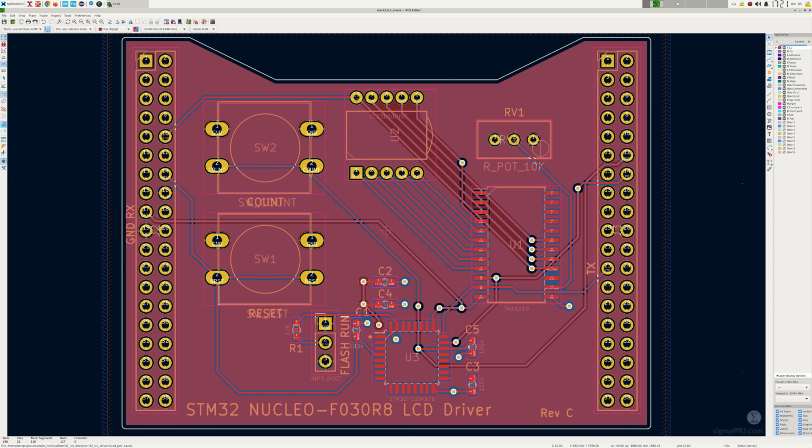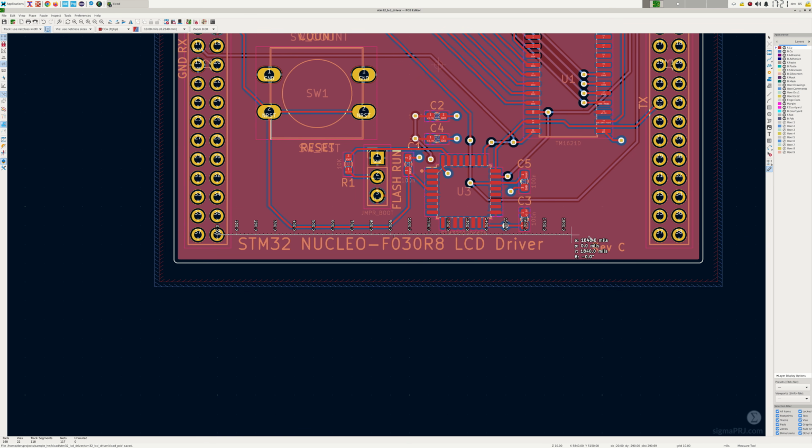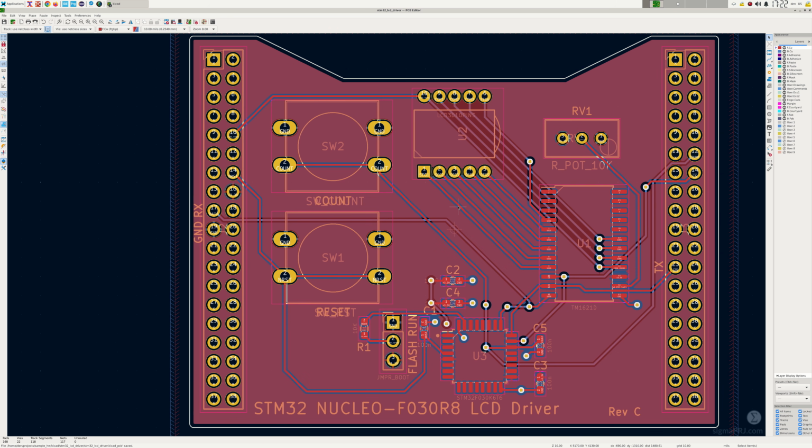Let's switch now to our PCB layout design. This has quite simple routing. It just contains 2 layers. And there is a principal measurement here which we have to follow. The distance between socket connector pins should be exactly 2300 mils in total. This way our adapter PCB will be pluggable into NUCLEO board without any issues. Here we can see the footprints are placed, used for our Titan LCD driver, potentiometer to adjust the LCD brightness, LCD component itself, and our Nucleo board connector headers.